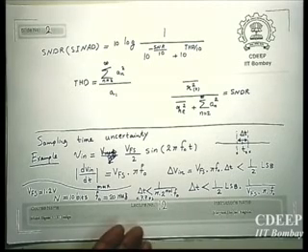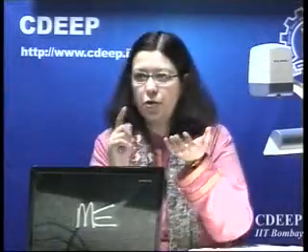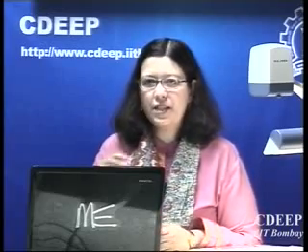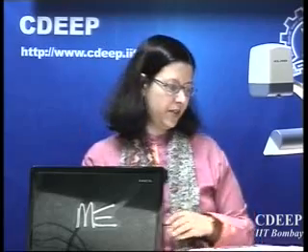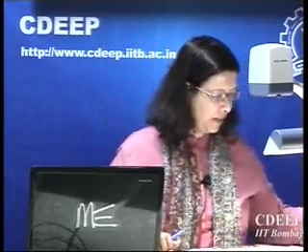And of course, when you design, you want to make it much smaller than this, because there are accumulated effects. You have this uncertainty in the sampling, and you have those DNL and INL effects, right? Therefore, you always need to make sure that the accumulated effect of all these non-idealities will give you one LSB error, not more than that. Inherently, an ideal ADC has one LSB, so you can add one more LSB, that is the best case. Not beyond that.